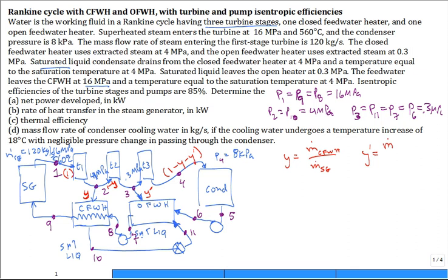You have 2 choices of Y prime. It's definitely the numerator that goes down to the open feed water heater. That's not the question. But is it divided by the mass flow rate that comes out of the second turbine stage, or the mass flow rate that comes out of the steam generator? You could work it with the second turbine stage, but the way we've written it, especially with the 1 minus Y prime coming out of the third turbine stage, it's this definition: m dot steam generator. Okay?